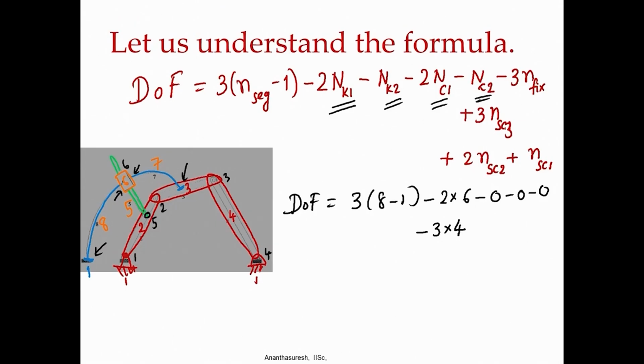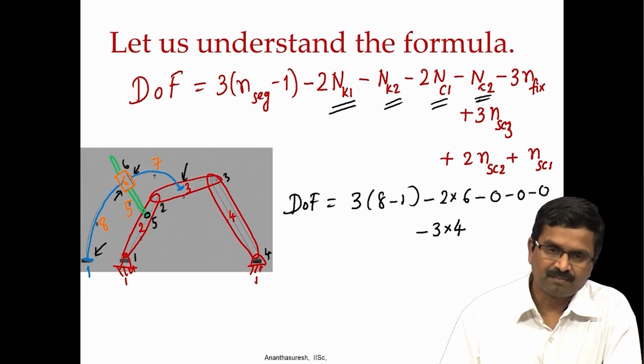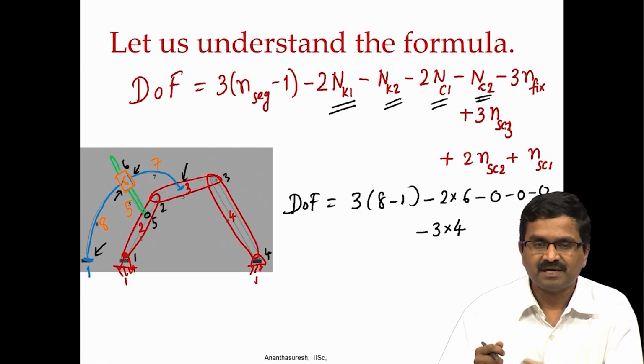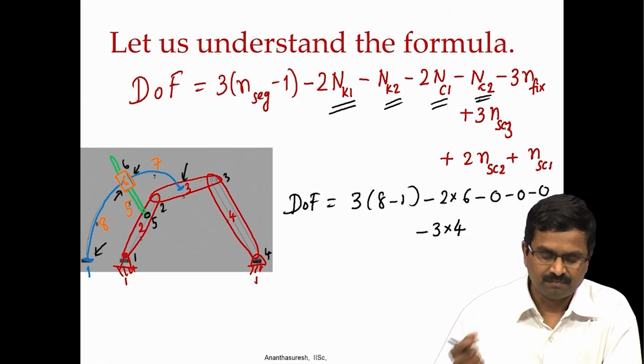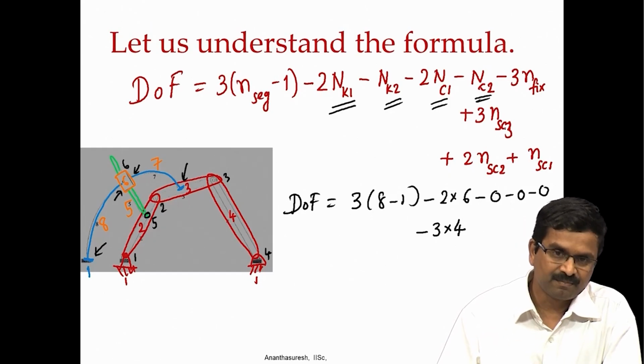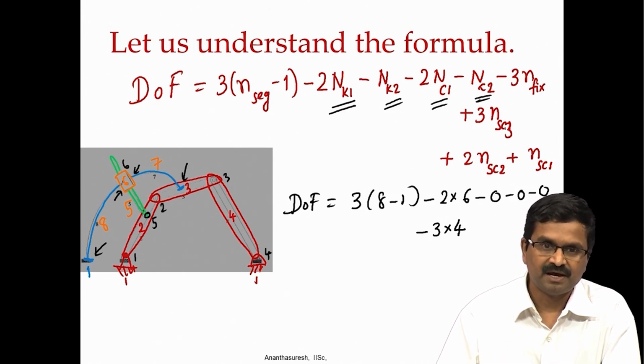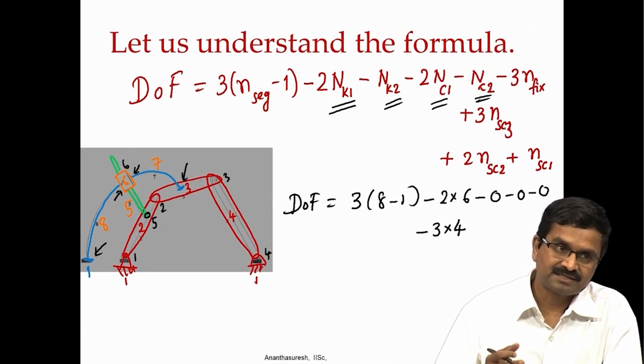we have this NC3, NC2, NC1, that is segment compliance. Choosing segment compliance we need a little practice, but when you are in doubt you take the full one. Let us say we have two elastic segments here, let us take segment compliance of both of them to be full in planar case, that is 3. Segment compliance refers to in what ways the elastic segment moves between the two bodies that it connects to. Okay. Now, elastic segment is like a joint also, because it allows relative freedom between two things. A rigid body would not allow, only a joint would, elastic segment would.